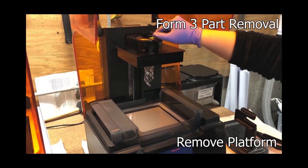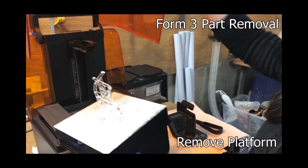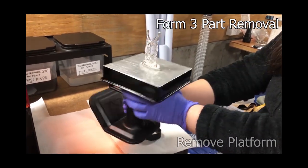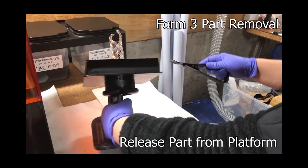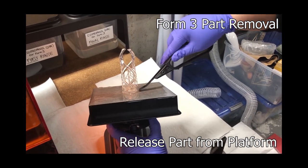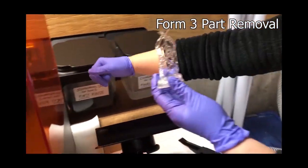You unclip the build platform. Now I always twist the build platform really quickly because I don't want any of the liquid resin in the build platform to drip around the printer. You use those two tools to remove the print out of the platform. And because I use mini raft, it did take a few tries to remove it, but there it is.